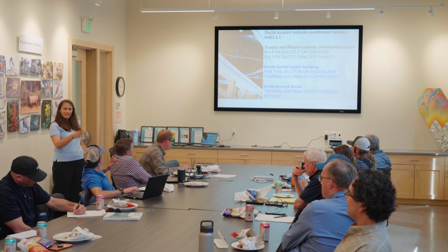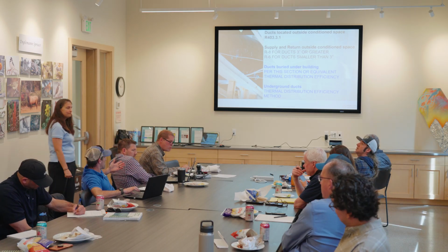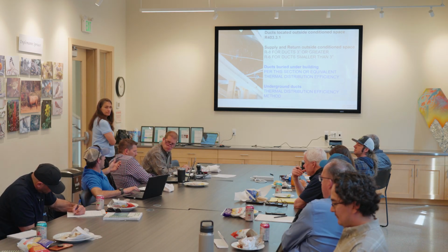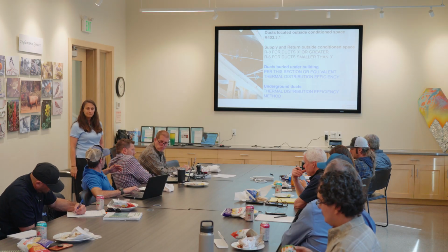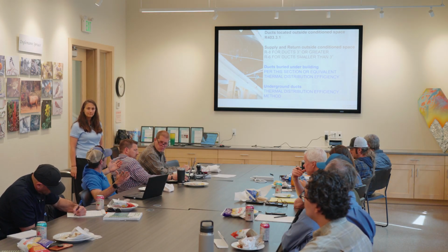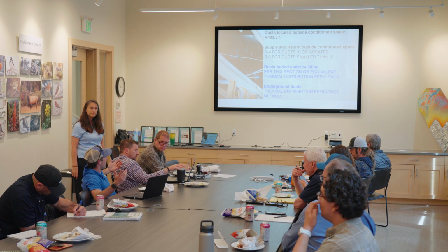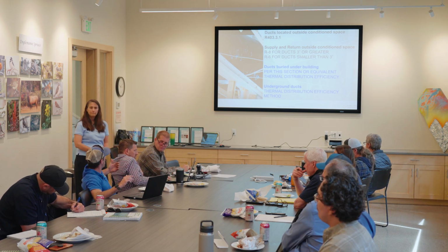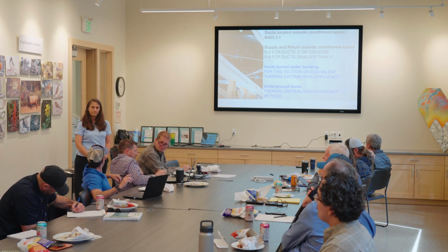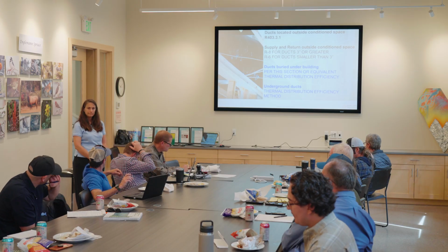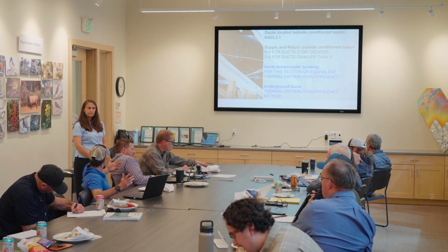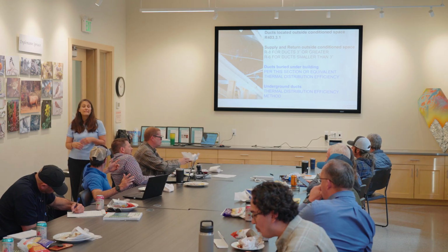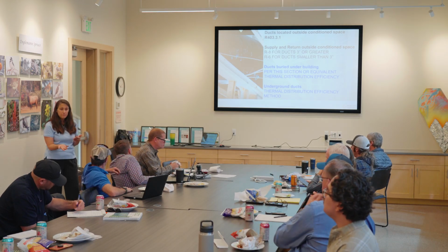Right. Yes. I actually thought this was pretty cut and dry as far as locating outside the conditioned space. It sounds like you're saying it's like a house that has supply ducts that go under the slab from a crawl space and pop up on the other side of the slab. Those are outside. That would have to be insulated, correct? You're saying it does not. If it's outside of the thermal envelope, it would have to be insulated.